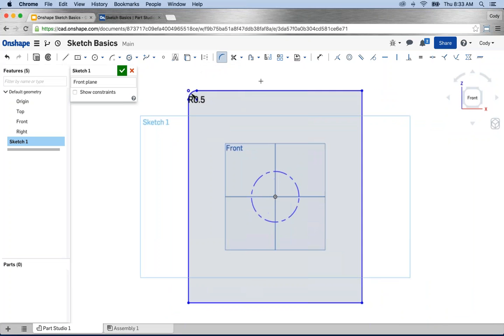There's one tip that I want to give you though, and that is instead of doing a single click on a point like I did there, you can left click and drag, and it will allow you to dynamically resize the fillet on the fly. So you can get an idea of what the size is. That looks just about right. Let go. Okay, that's a 5-inch radius. It's a great way to eyeball the different fillet sizes and change it on the fly. Again, the main thing there is you left click and drag to get that behavior.